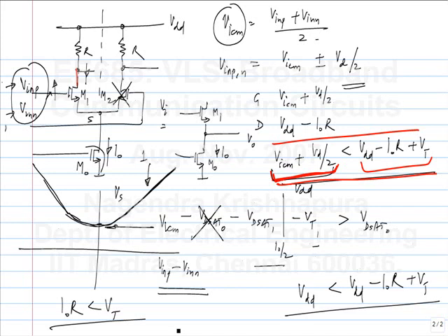Okay. So what happens if you do that? So what you're saying is true, and sometimes you do use it like that. You make a compromise. So what happens if it's not in saturation throughout? What's the effect on the characteristics of the gate? So basically you need more voltage to switch it completely, that's all. So we'll start with the assumption that it has to be in saturation. And in fact, you do design it in many cases where it has to be in triode simply because you can't do it otherwise. Okay. But it is best if it is in saturation.